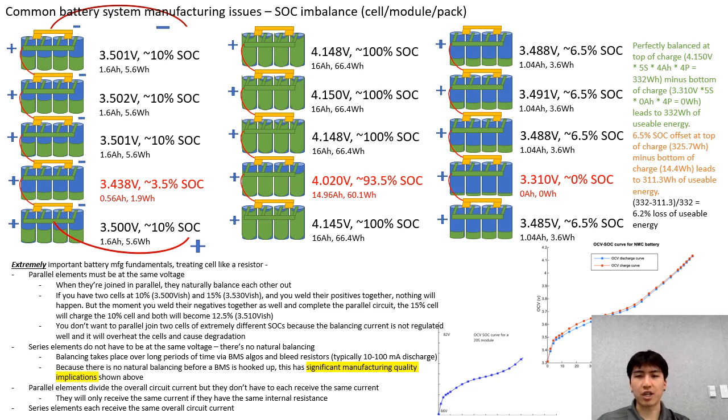So let's say a cell, you charged up from 0 to 50%. Now after an infinite period of time, your open circuit voltage should be around 3.68, 3.69 volts-ish. And that's the main reference table that everything is based off of.